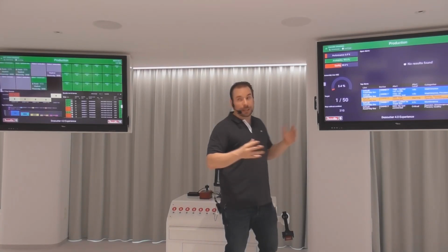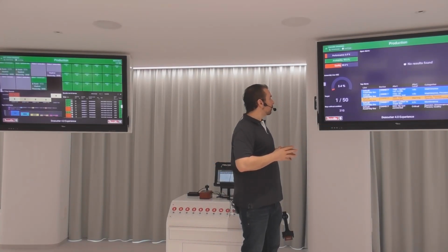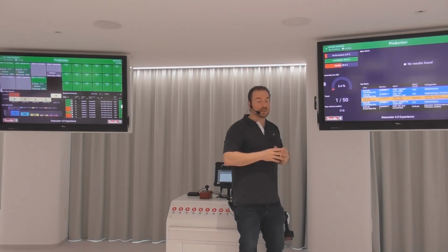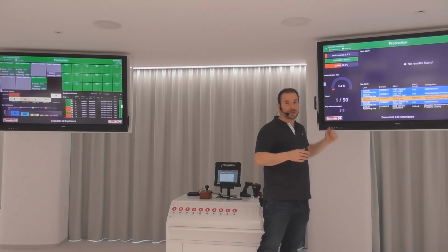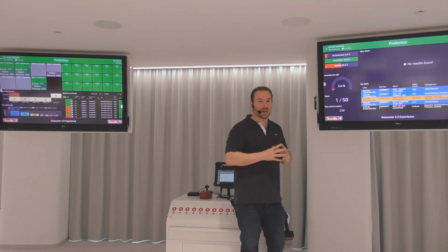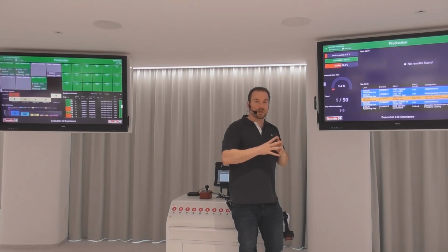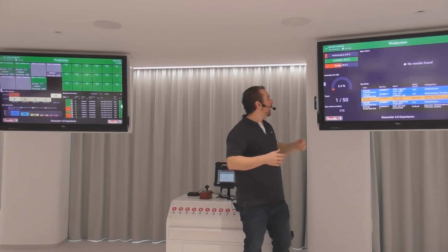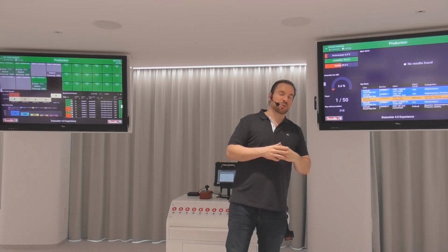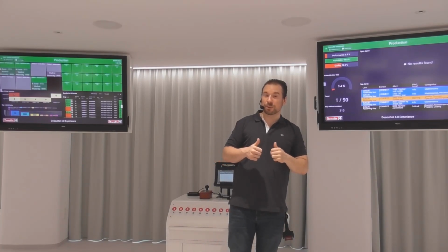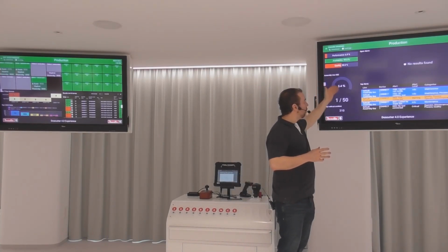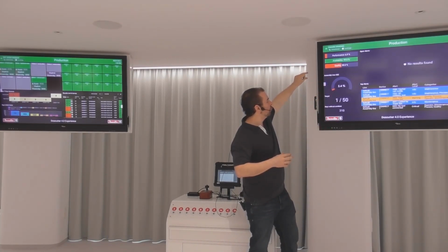If I have a look at my two examples of the dashboards, which I have over here, you see that this part over here is showing the performance, which obviously is not the best because I produce only one product out of 50. I can see my availability, which is almost fine. Availability decreases when the line is not operational, obviously. And I can see my quality, which is at 50%, which means that I was trying to produce two products, but I only managed to produce one properly, so I might not be the best operator. And then you have the OEE overview, which is basically a combination of the three above.